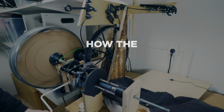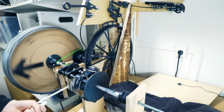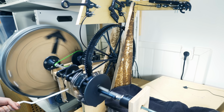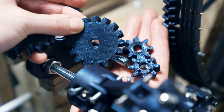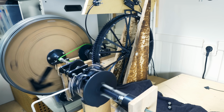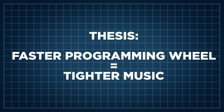I want to see how the speed of the programming wheel is affecting music tightness. And this is something that I've been thinking about a lot. And thanks to this brilliant prototype rig, I can test this very easily. So what I'm going to do is run a test at normal speed, and then I'm going to change out the gear for a gear twice its size to make the wheel go twice as fast. And here's my thesis. I think the faster wheel will play tighter music.